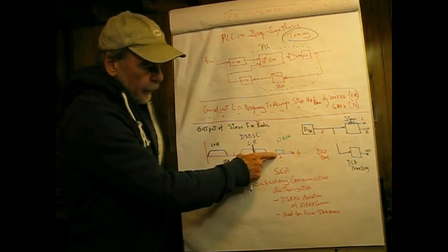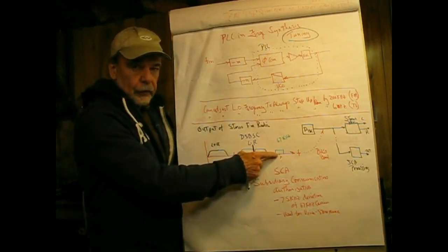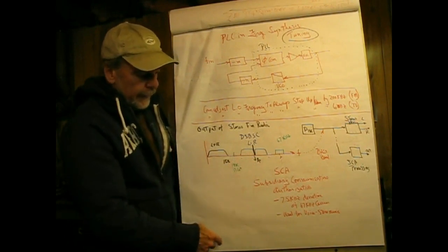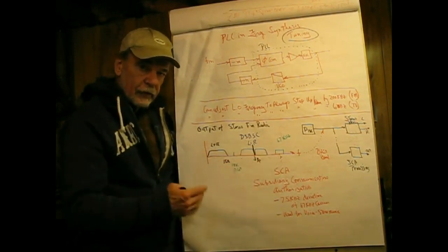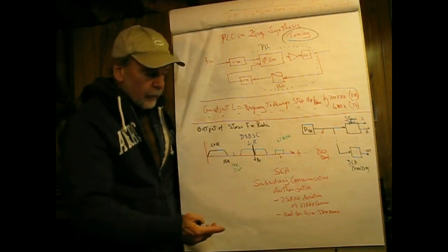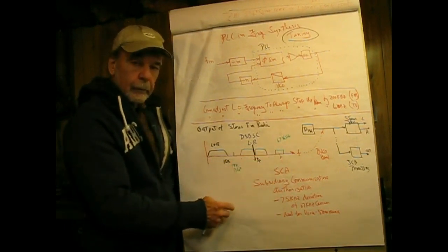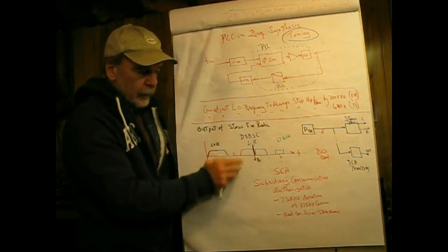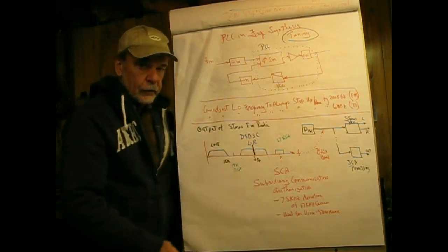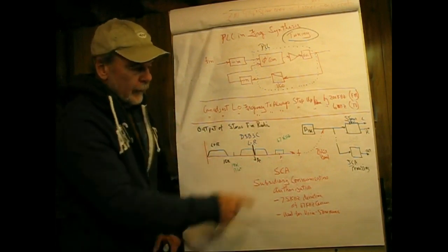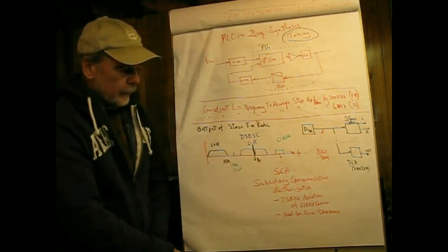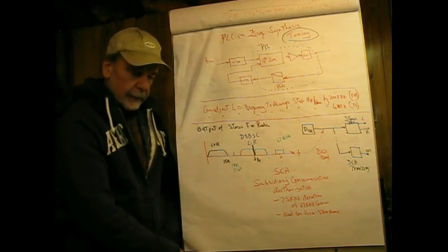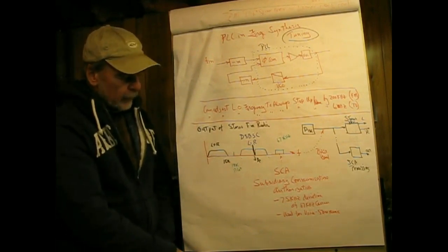And this here is a frequency modulated signal. The carrier is 67 kilohertz, and it's only permitted to deviate 7.5 kilohertz. So this is relatively low quality compared to the high fidelity part of the signal which resides up here. So a bit of deviation is used for this SCA channel riding on the baseband signal.